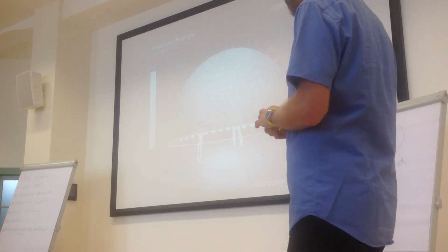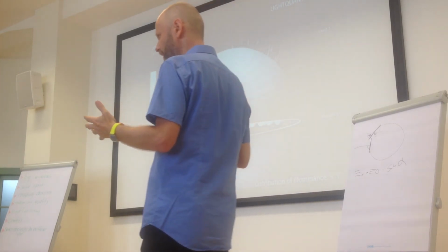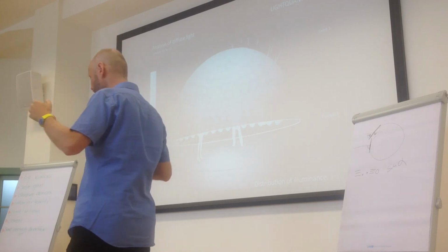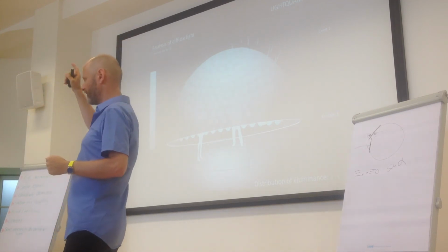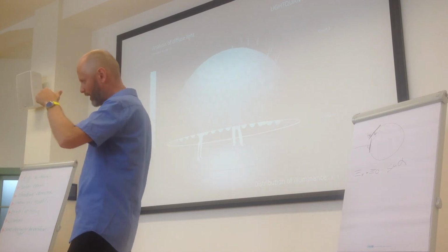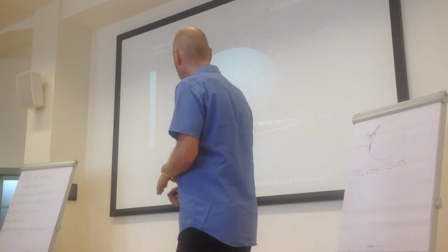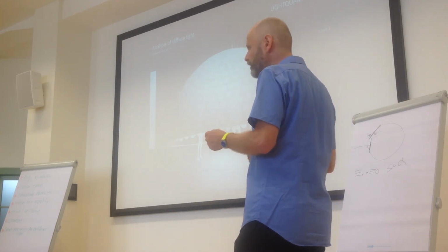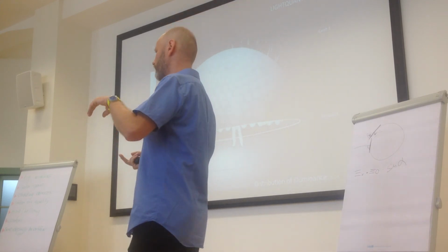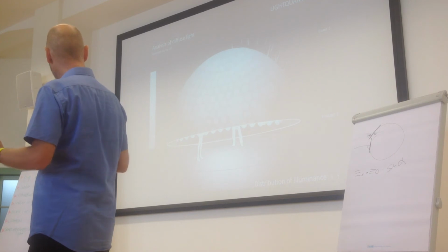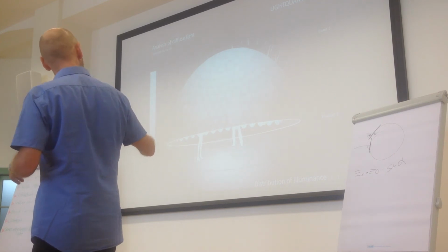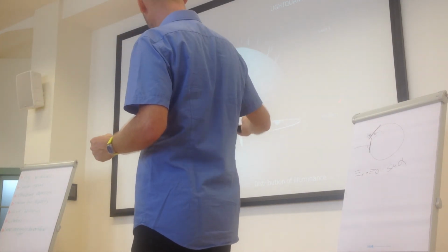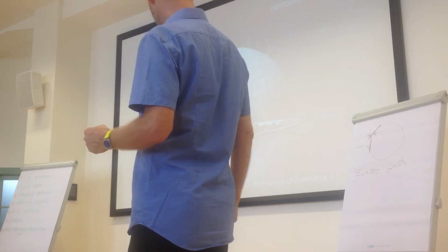Remember, or imagine you have a rainy day and you have a look at the distribution of light in the sky. You will recognize that the brightness at the zenith is about three times higher than down on the horizon. And this characteristic is equal for the North Pole, for the equator, for every place on Earth. A constantly overcast sky has this typical brightness distribution of 3 to 1 between the zenith and the horizon.